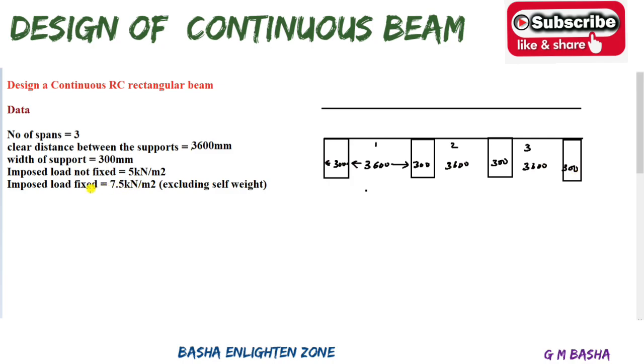Then what is our first step? Each and every time, along with the given data, we have to design for M20 grade concrete and Fe415 steel. So our first step is to choose the suitable effective depth and overall depth for the beam. For that you can take the span to depth ratio, that is the L by D ratio. We know that the L by D ratio should not be more than 26 for continuous beams, so we can select a value less than 26 only. Here I will take the L by D ratio as 15.